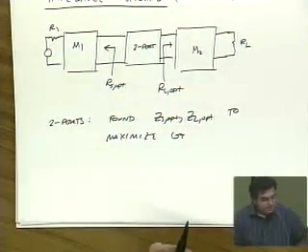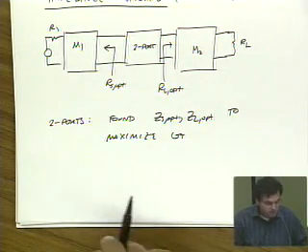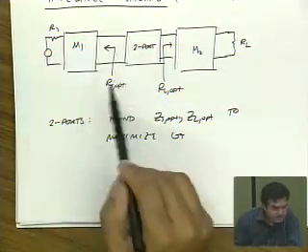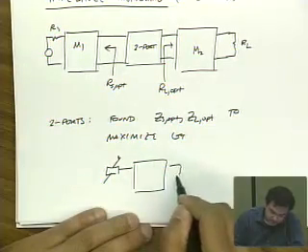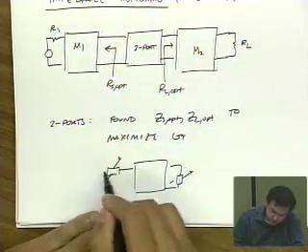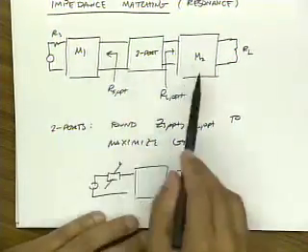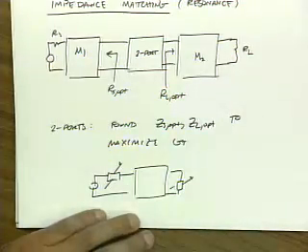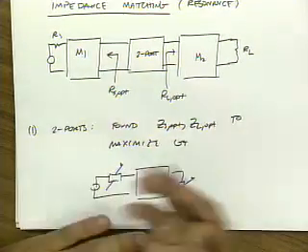How about other cases? Why else would you want to provide an impedance match? Can someone think of other situations where an impedance match may be useful? So in essence, this is kind of the knob that we were talking about. This is the ability to tune the source and load to get the maximum gain. In practice, this is how we do it. We can't really change the source and load, but we can design matching networks around our device. But what are some other reasons why we'd like to play the matchmaker, if you will?